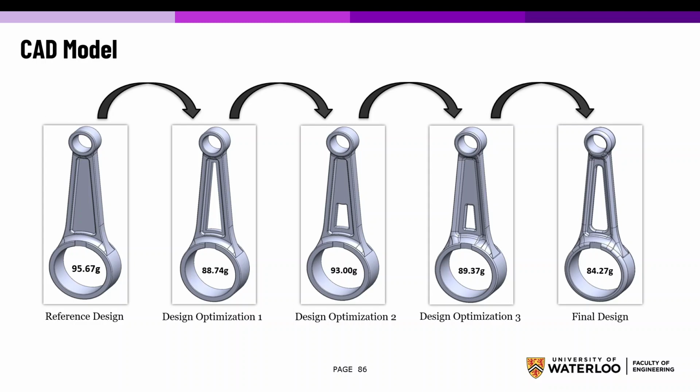And we dropped about 6 or 7 grams here by doing the first design optimization where they just arbitrarily put a hole. And then they said, okay, well, let's change the size of the hole because this now caused some stresses that were too high. And you can see how they've evolved over time. They've added some mass back, they reduced some more, and then they kind of fully optimized the design there at the end.